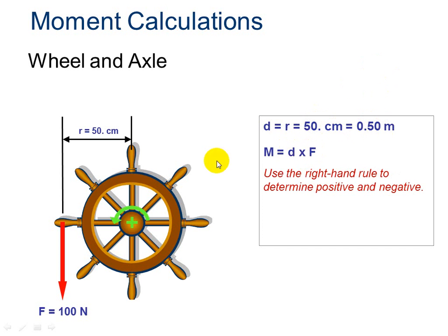and then I need to consider when I exert a force here, what direction is this wheel going to want to spin? It's going to want to spin counterclockwise. Counterclockwise direction, I'm denoting an arrow of this way it's going to spin, and then I write a plus because when I calculate my moment at 50 Newton meters, I want to have a positive answer because I've got counterclockwise rotation. That's a positive moment.